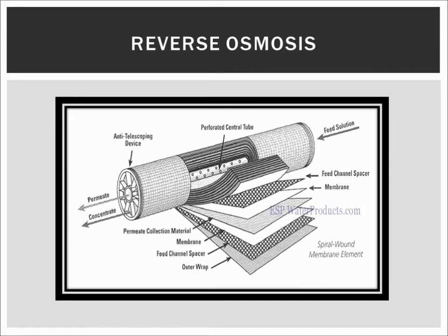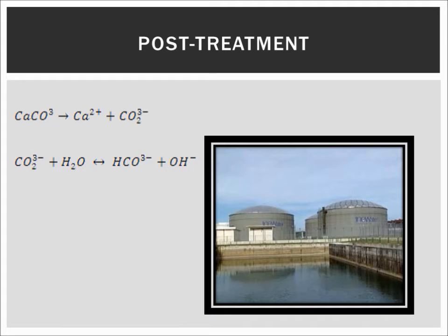For this plant, we will incorporate a two-pass split partial RO system. To determine the necessary parameters for our treatment, IMSDesign will be used. This is a program provided by Hydranautics that allows the user to determine the most efficient membrane combination while evaluating all necessary parameters for design. After evaluating 4 different membrane combinations, we determined that the SWC6 and ESPA2 Max by Hydranautics is the most efficient.